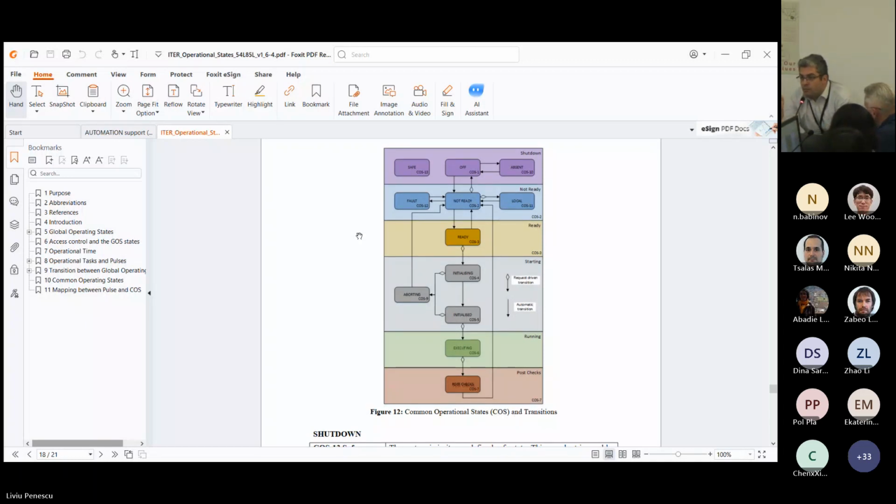So if you're in ready and the countdown arrives, so SUP says countdown, your next state is abort because it's after the countdown. But if SUP has not triggered the countdown yet, then your next state is not ready. Okay. Right? Okay, so if in the ready state there is an interlock or safety kick out, then we go to abort, and not back to ready, not ready, sorry.